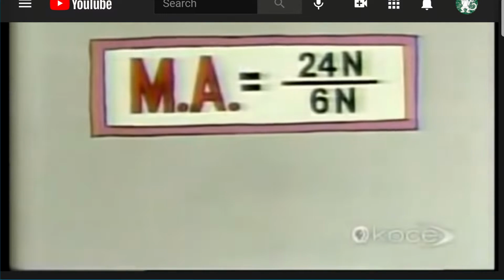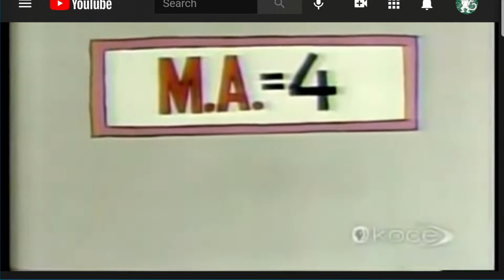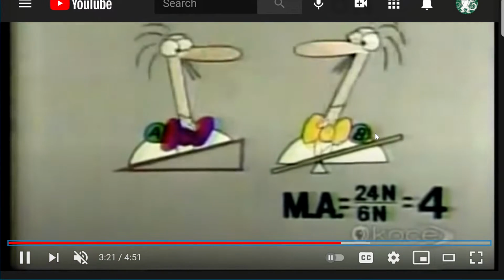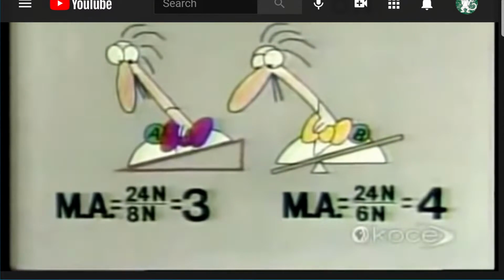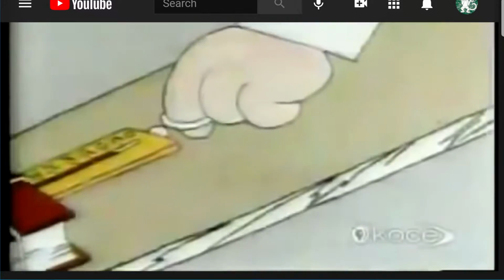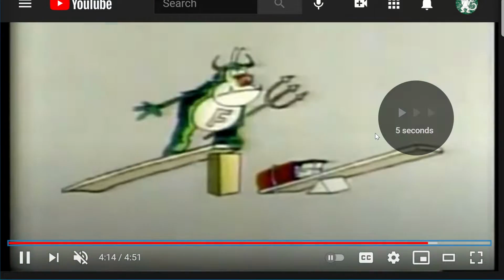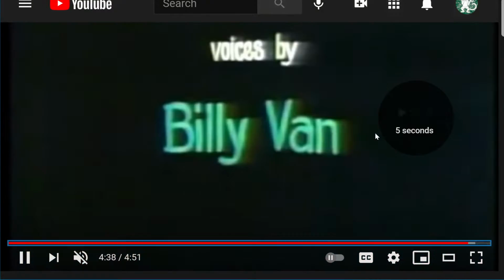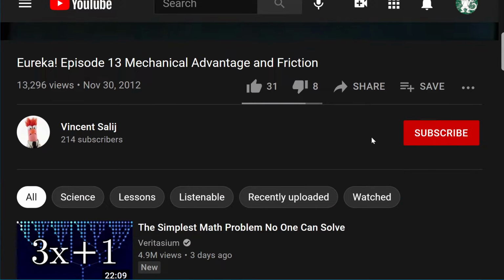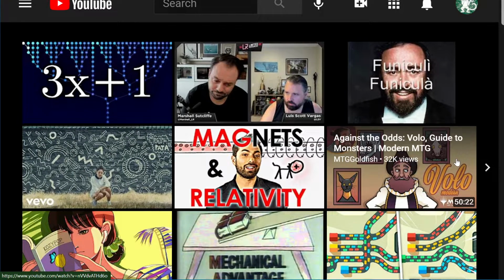They don't really talk about this. They talk about the mechanical advantage, and they've said the mechanical advantage is 4, but this guy's going to use a ramp, and his should be 4. He predicts that he has a mechanical advantage of 4, but he doesn't get it. He actually only gets a mechanical advantage of 3, and the reason for that is friction, right? And so friction reduces the effectiveness of the lever. Then it says, hey, friction's important, don't worry. Now, it explains the difference between friction and velocity ratio, but what we need to worry about is